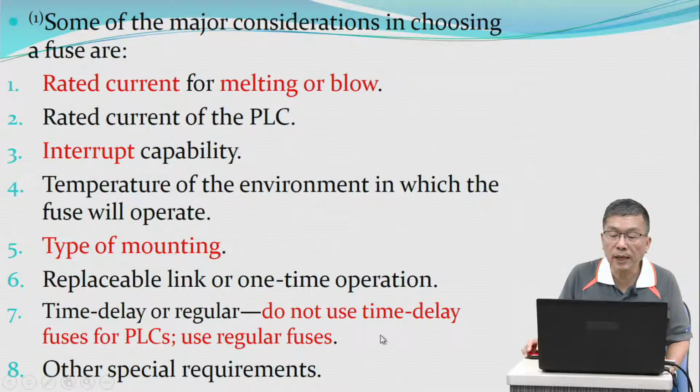Do not use time delay fuses for PLC. Use regular fuses. Other special requirements.